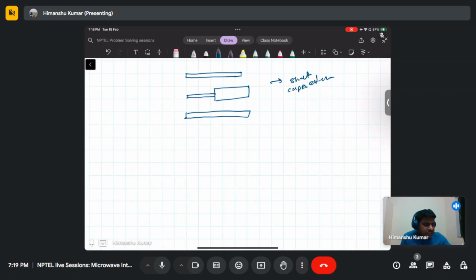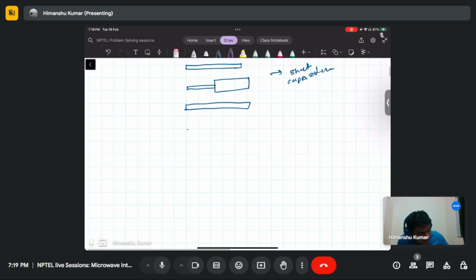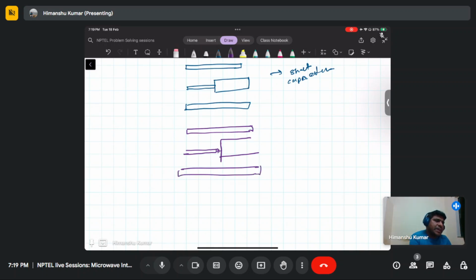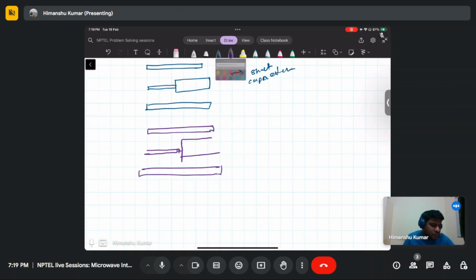Also, you can construct a gap implementation. You take the transmission line and put a gap, and this distance controls the capacitance between the two lines. This can be constructed as a gap capacitance and modeled as a capacitive coupling. You can also model inductive coupling.